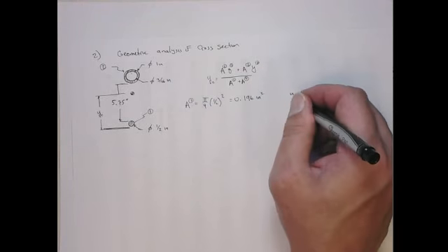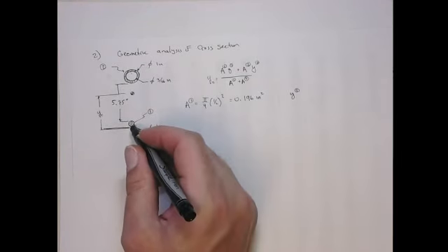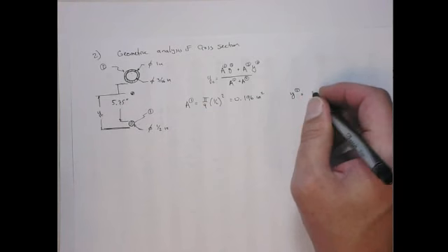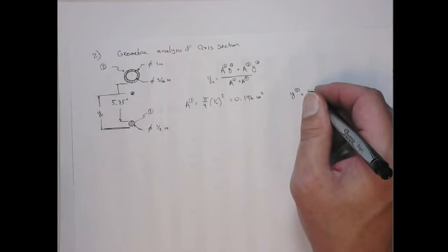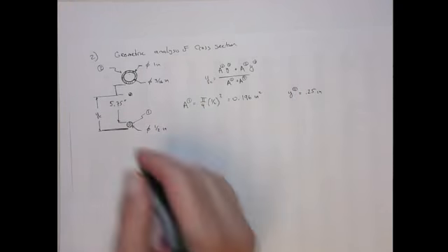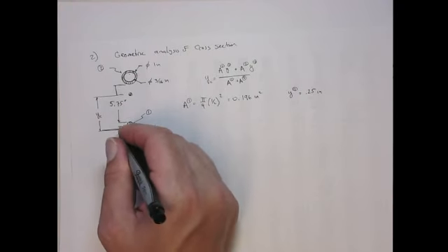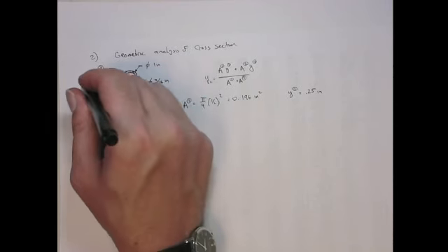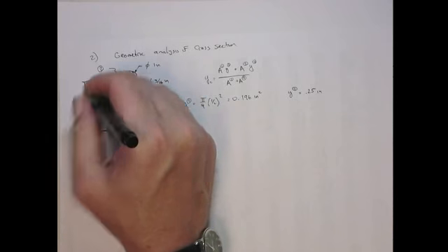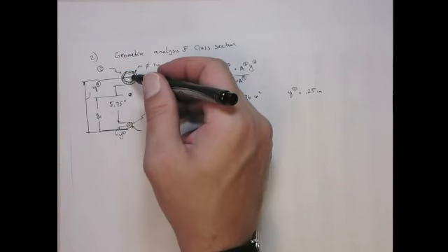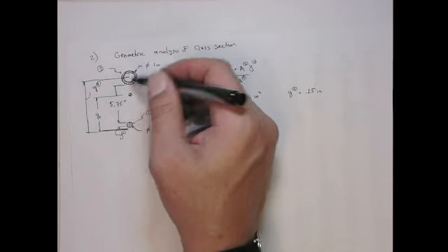The distance from this low reference to its geometric center is half the diameter or the radius. So that's going to be 0.25 inches. Okay, right. That's just this distance. That's y1. This distance here is what I'm calling y2, the distance from the reference to the geometric center of the second body.